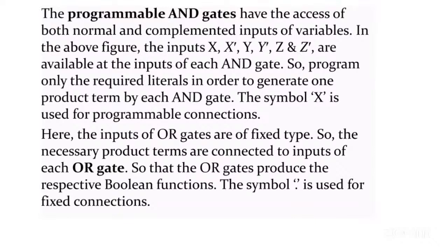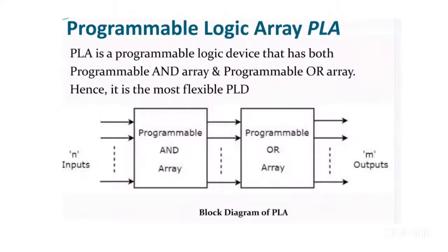Here, the inputs of OR gates are of fixed type, so the necessary product terms are connected to inputs of each OR gate so that the OR gate produces the respective Boolean functions. The symbol is used for fixed connections.